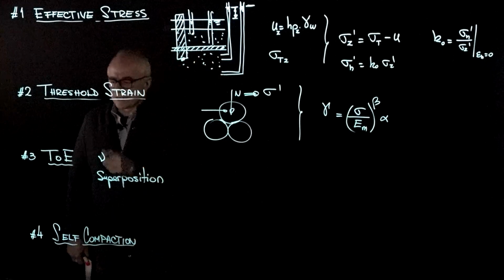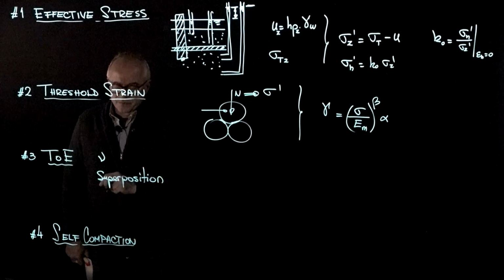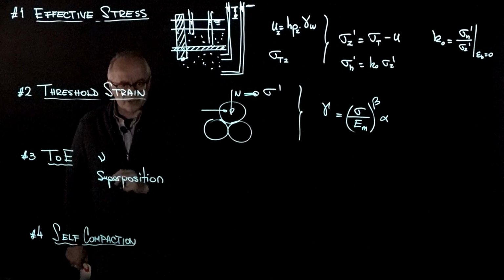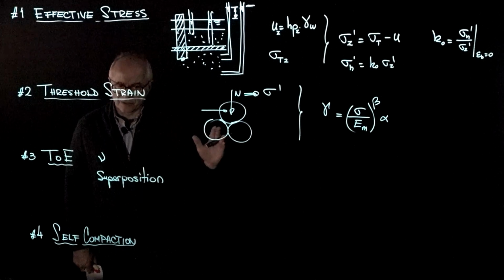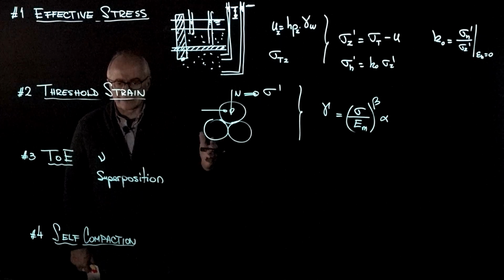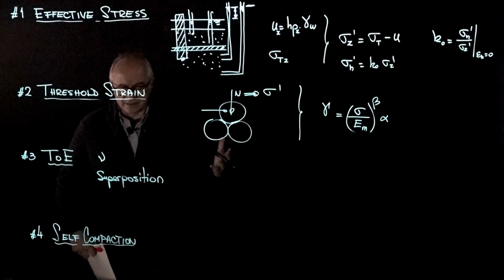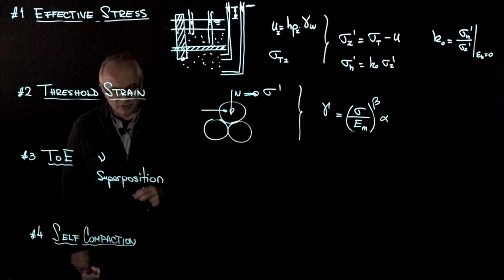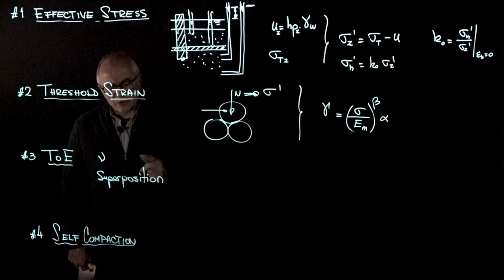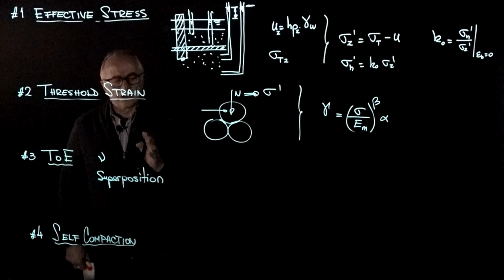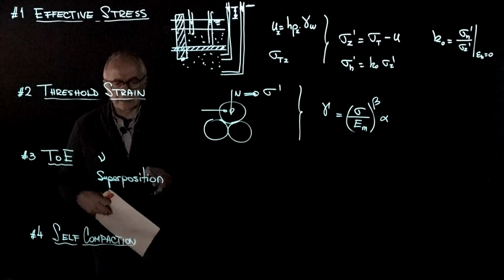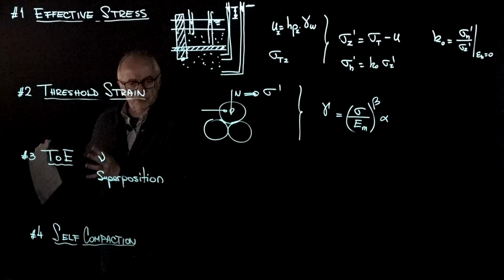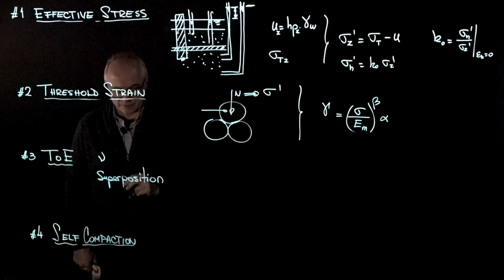Similarly, for theory of elasticity, we reviewed the concept of Poisson's ratio, and there is a video on that, and the importance that there is a limiting value for Poisson's ratio for theory of elasticity to remain consistent, for the bulk stiffness to remain a positive value compared to the Young's modulus. So that was 0.5, but 0.5 is also the Poisson's ratio where there is zero volumetric strain, and it comes back from the definition of volumetric strain for a small strain deformation.